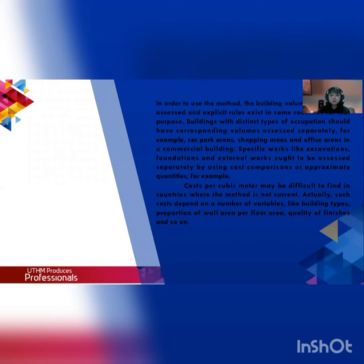In order to use this method, the building volume must first be assessed. Buildings with distinct types of occupation should have corresponding volumes assessed separately, for example, car park areas, shopping areas, and office areas in a commercial building. Specific work like excavations, foundations, and external work ought to be assessed separately by using cost comparisons or approximate quantities.